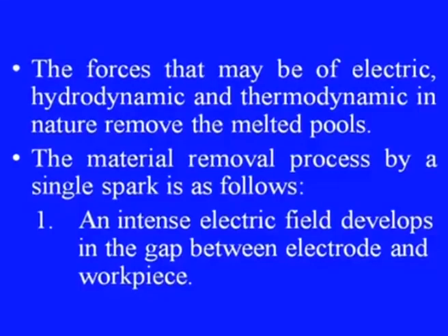Both the tool as well as the workpiece get eroded. At the end of the pulse duration, a pause time begins. The forces, which may be electric, hydrodynamic and thermodynamic in nature, remove the melted pools.